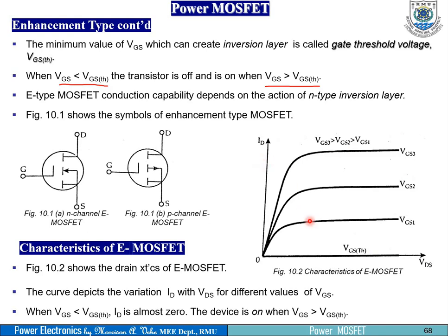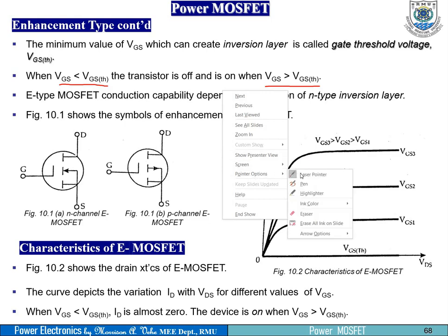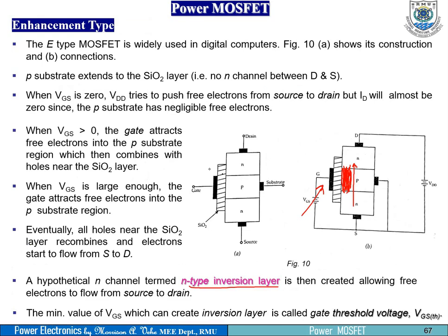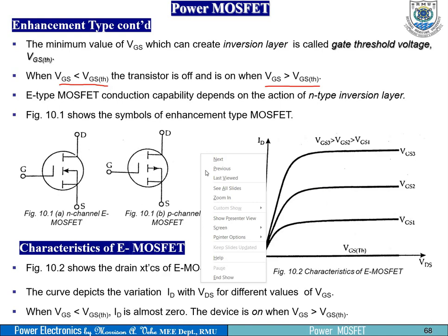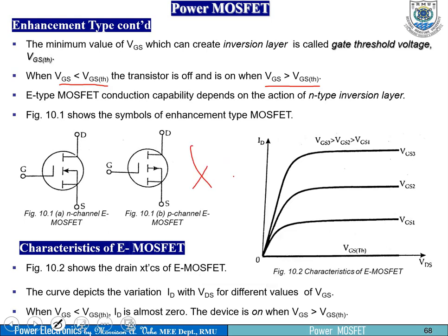Just like you have the characteristic curve of a transistor configured in common emitter mode, we are looking for the output curve. So what then do we say? We are just trying to draw a curve of collector current versus VCE, the collector emitter voltage. It is a function of what? IC versus VCE. That is the output characteristic curve.